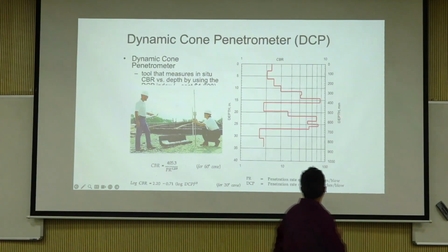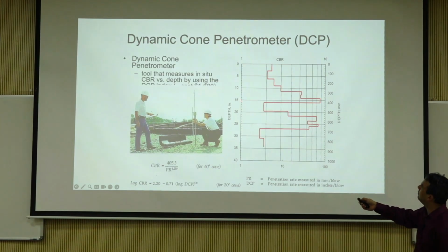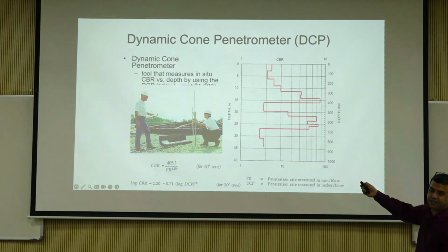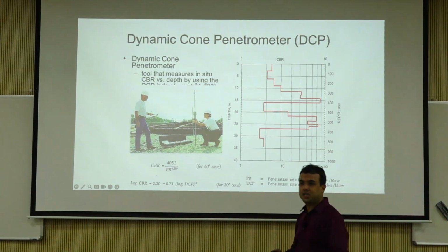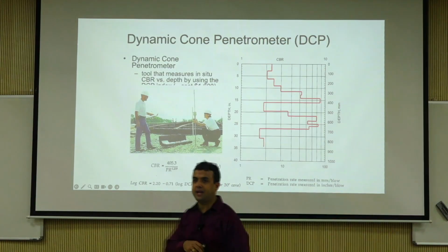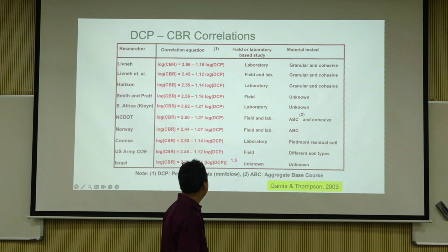This is what you would end up with by taking the penetration rate and analyzing DCP data. You can find like a CBR profile, and then you can take, let's just say your area of interest was 6 inches or something. Then you can say, okay, over the first 6 inches, my CBR is on an average this much and stuff like that. That's how soil conditioning in the field happens when you're trying to build test sections, or when you control water and stuff. We can do that.